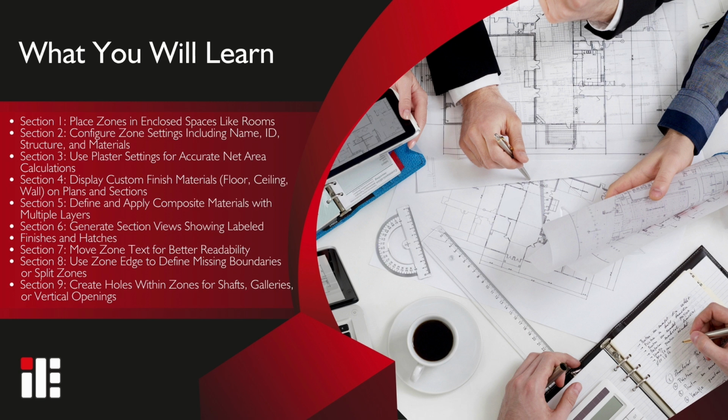In this video, you'll learn how to create and manage zones in ideCAD architectural to define interior spaces and organize finish information. We'll show you how to place zones in enclosed areas, customize zone settings like name, ID, materials, and display labels, and accurately calculate net and gross areas using plaster settings.